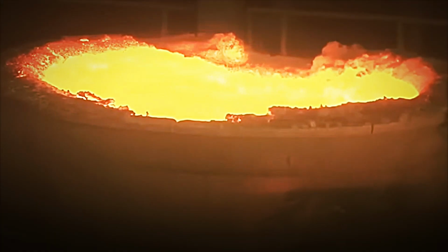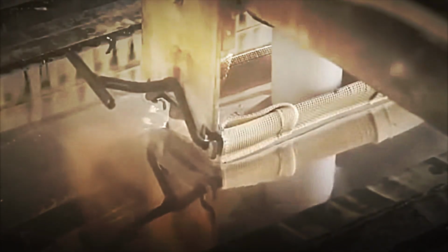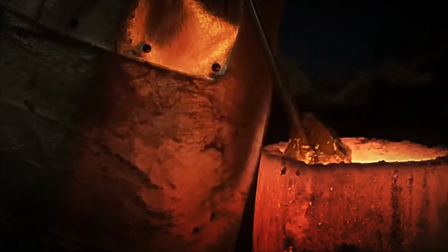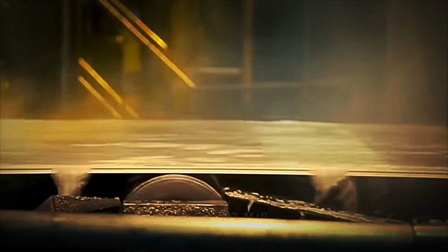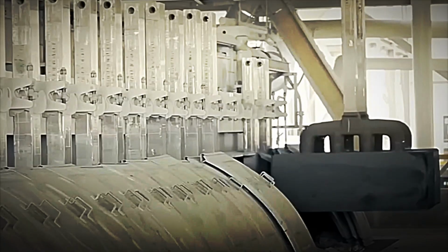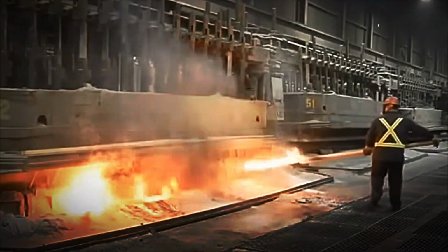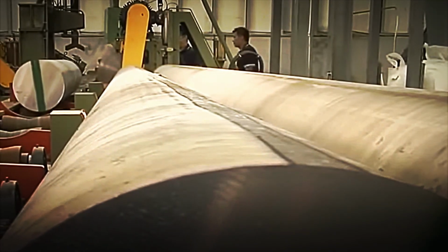Each ingot bears a code that allows its origin, composition, and production date to be traced. Once the aluminum ingots have been melted and solidified, they are not directly used in industry. To convert them into useful materials, they must first undergo a transformation process that converts them into thinner, more malleable sheets, coils, or profiles. The process begins with the preheating of the ingots in specialized furnaces that reach temperatures exceeding 500 degrees Celsius. This step is crucial because the heat makes the metal's internal structure more flexible, facilitating subsequent thickness reduction work without the material cracking.